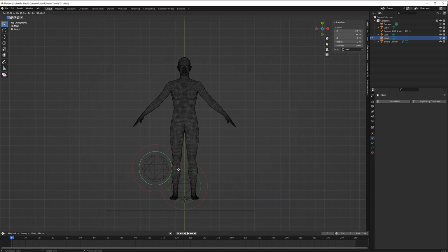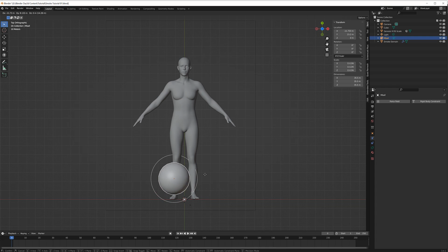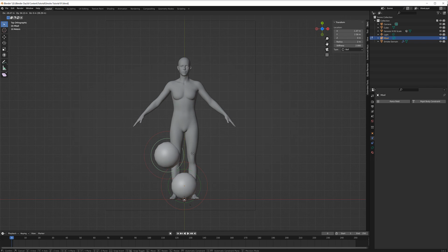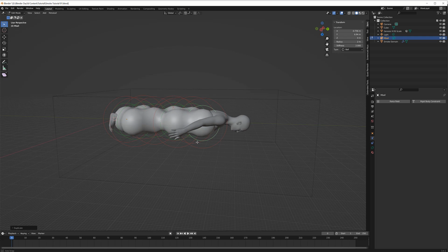And when I hit Shift D, it creates another metaball here. Let me go to solid mode. There we go. I use Shift Z there to go in and out of wireframe in Blender. So I just created this second metaball in edit mode there. And when I drag that around, you can see it kind of goopily sticks to the first one. So using Shift D and the grab controls, I'm going to create a sort of pillar or column of smoke. You can move these in all directions and rotate them and scale them to create different little protuberances in your smoke.